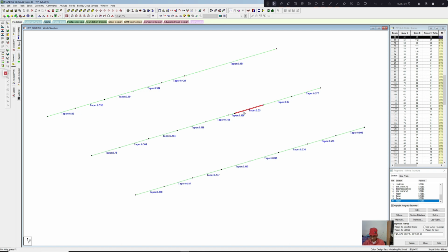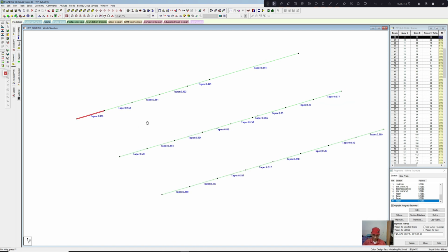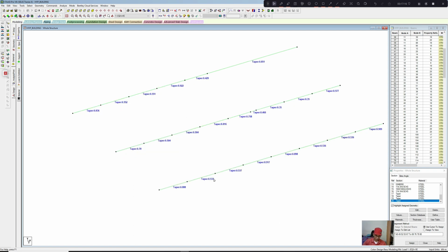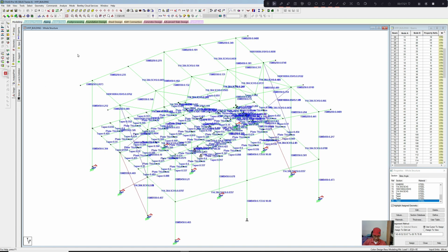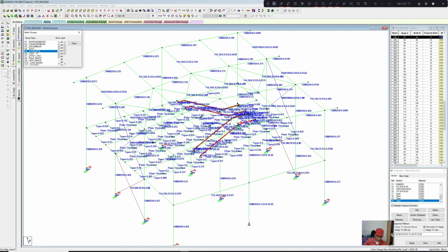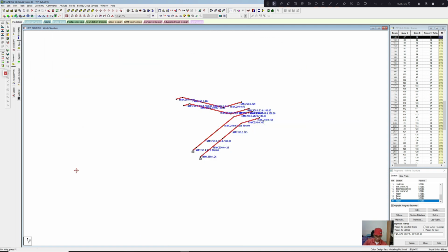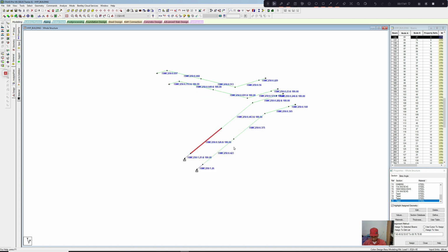So this is 0.577, 0.466. Whether there is a possibility of optimization or not, we'll cover that in the next section. So our main beam has been okay. Now view whole structure. Now select by group name, stringer. Let us see. The stringer size is 250 mm. Usually 250 mm is the most practical one.